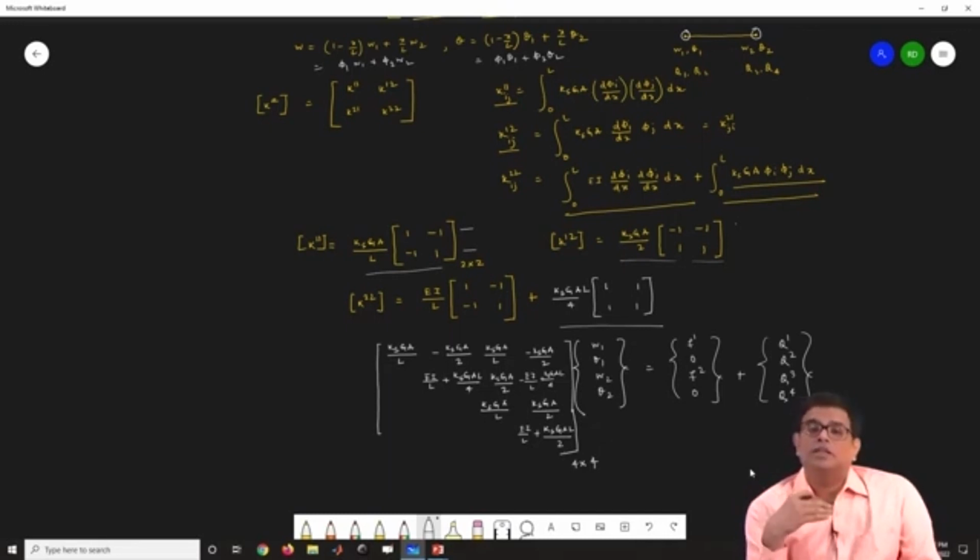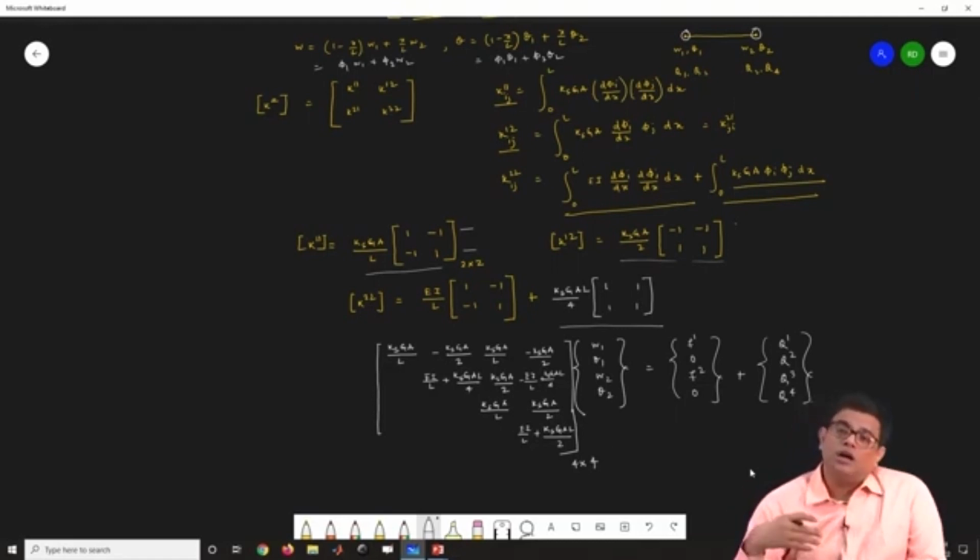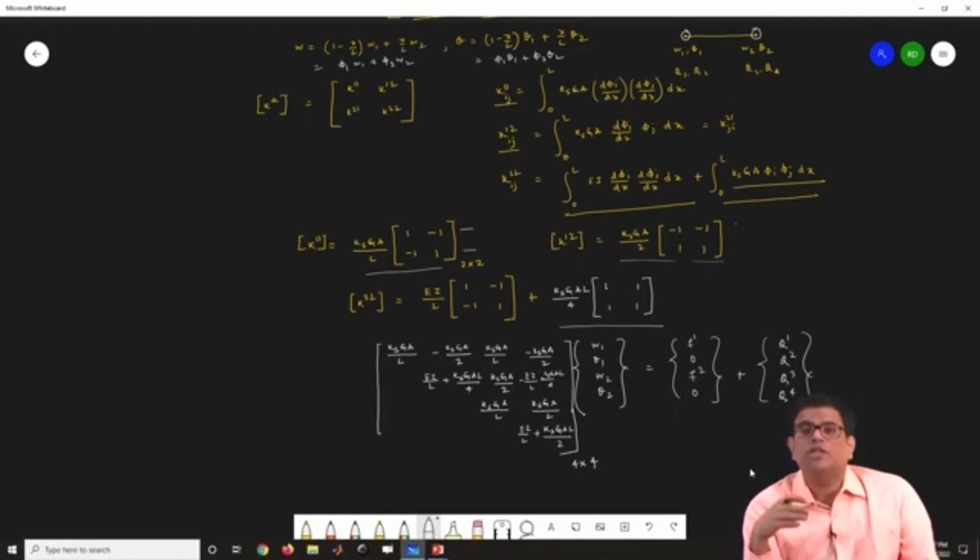For that, there is a different variational principle, which we probably will not cover here. For instance, the Hu-Washizu variational principle, or the two-field Hellinger-Reissner variational principle, and hybrid kinds of formulation, where stresses as well as displacements are interpolated. That kind of mixed formulation is also helpful to alleviate locking in finite element problems.